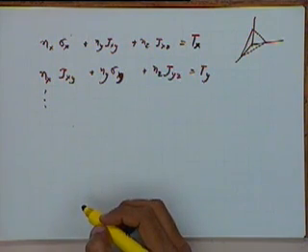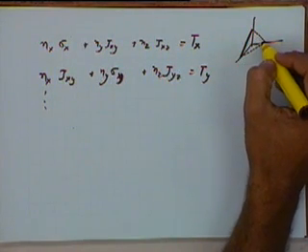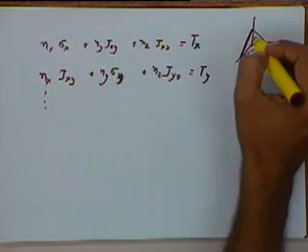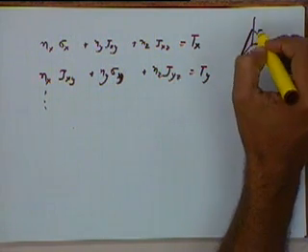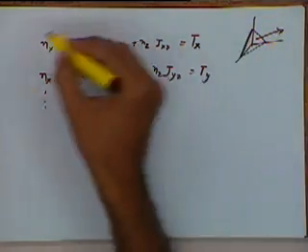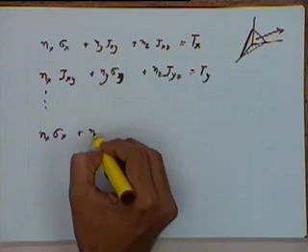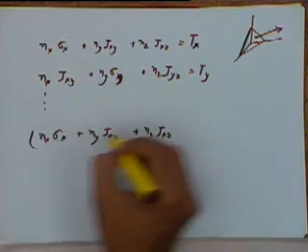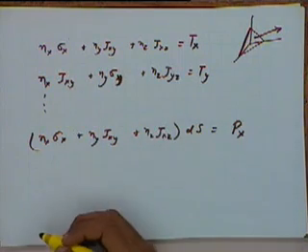And a similar equation for the third direction. This is for the tractive loads acting on the surface, that is, forces per unit area. But if there are any point loads on the surface, then our equations will be different. If in addition to the tractive force we have a point load acting like this, we will have to write nx sigma x plus ny tau xy plus nz tau xz, multiplied with dS, equal to a point load in the x direction.